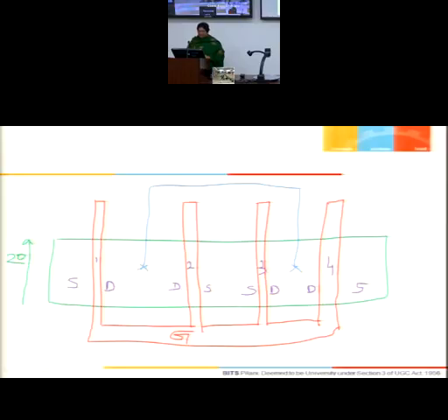Now remember, if you make a contact here, the contact to poly separation must be 2 lambda, and the contact to poly separation on this side must be 2 lambda, and the contact is 2 lambda by 2 lambda. So this total junction length has to be 6 lambda.